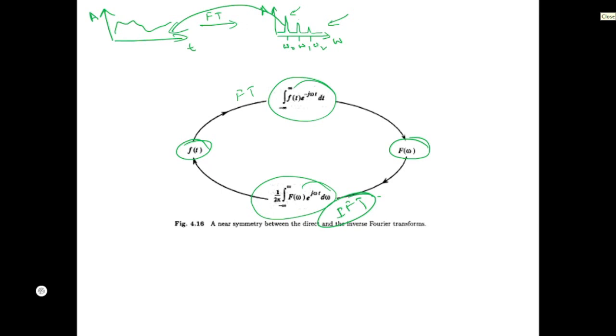Another important thing is that from here it is quite easy to determine your unwanted frequency components. For example, when we acquire biomedical signals, one of the common noises is power line interference.